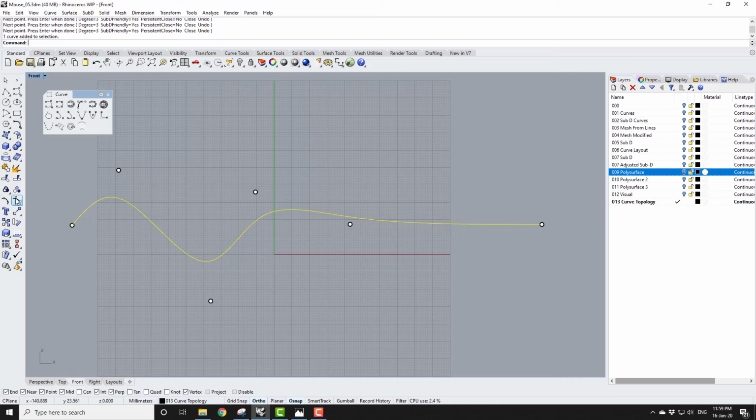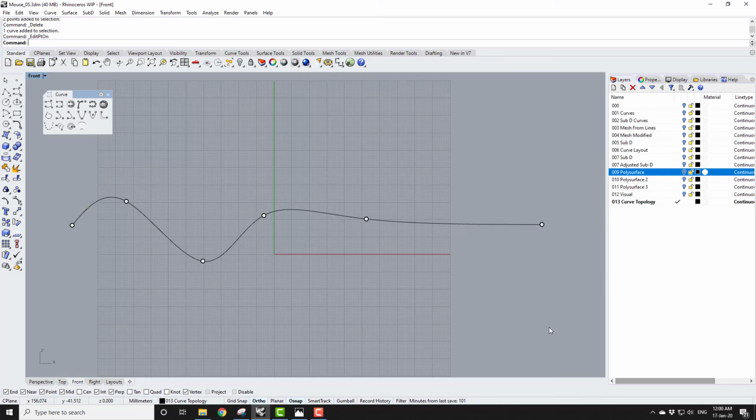If I visualize the control points of an open SubD curve, then I'll see two hidden constrained control points that sit between the first two and the last two live picked points. If we look next at the interpolated curve, there's a much more straightforward relationship with edit points in SubD friendly curves.